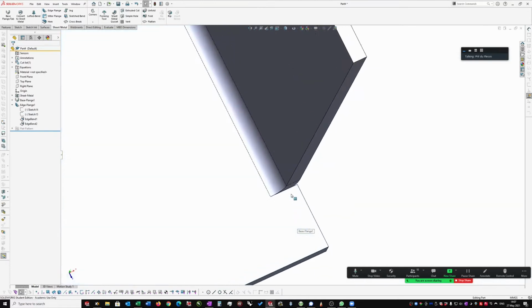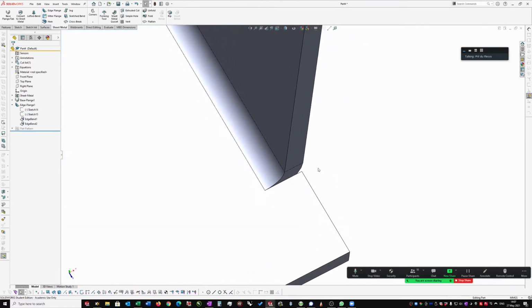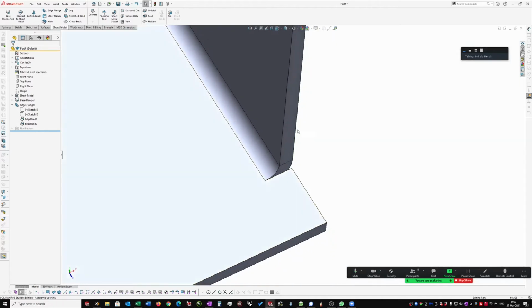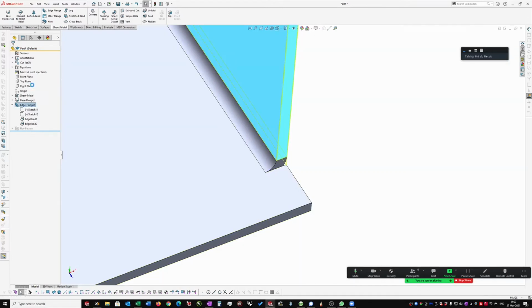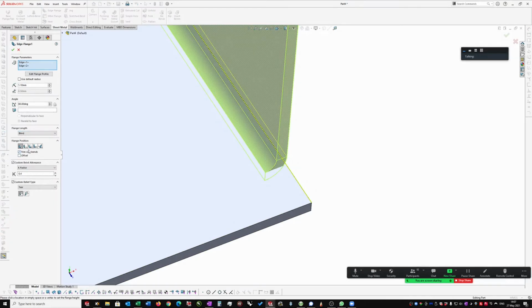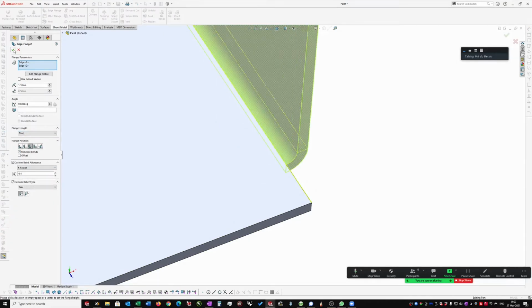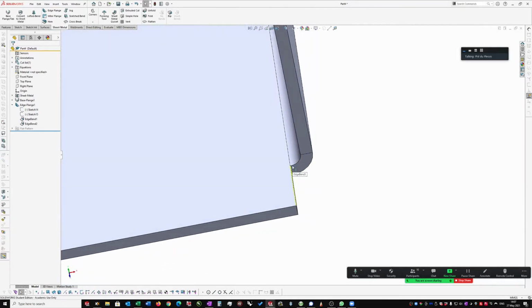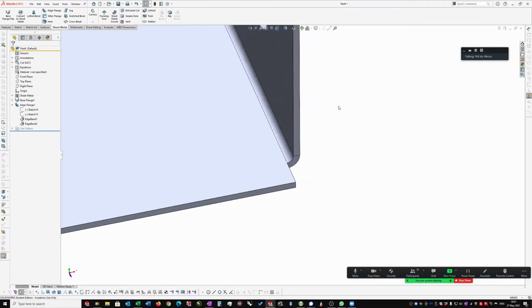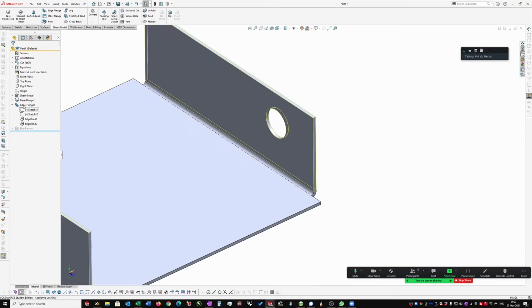Right, so you can see now I'm going to have to cut into it. If you can picture in sheet metal, you'd have to cut a slot in there without any relief. How do you get that piece to bend from this piece without having cut a slot in it? So typically a tear relief you would use in this configuration. You would go to that one there. Now you can do that bend without there being too much stress on that point. Okay, so that's how you do that. That's where the bend reliefs apply.